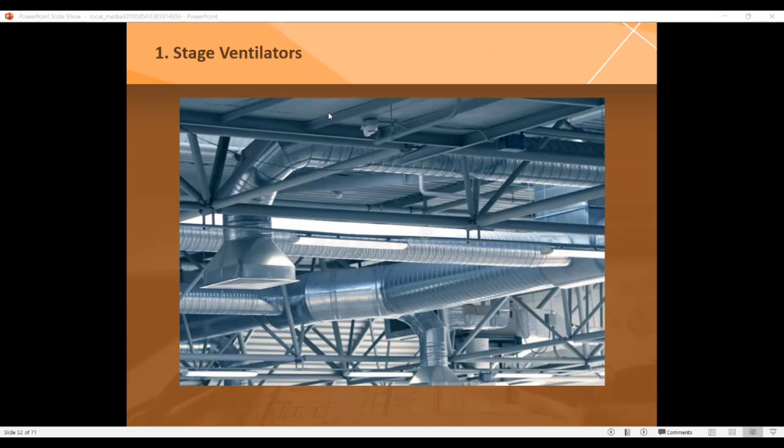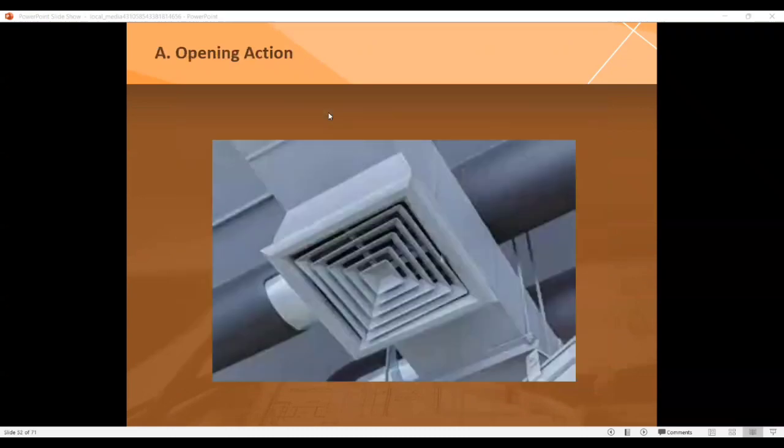Next is the opening action. Ventilators shall open by spring action or force of gravity sufficient to overcome the effects of neglect, rust, dirt, or expansion by heat or warping of the framework.